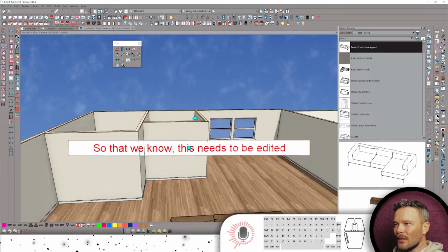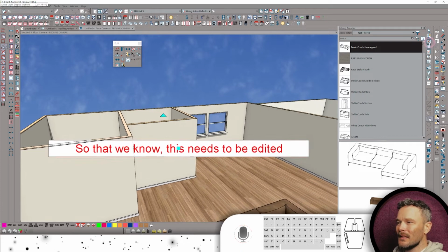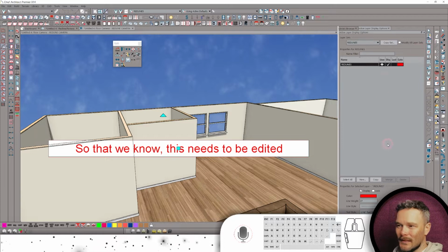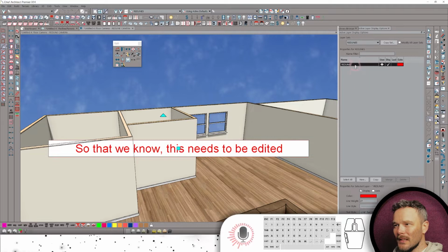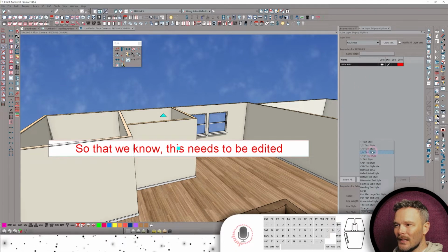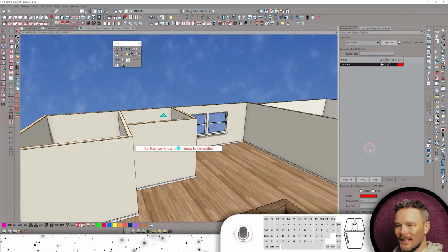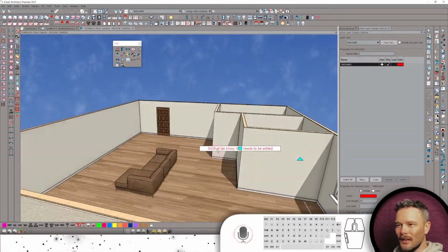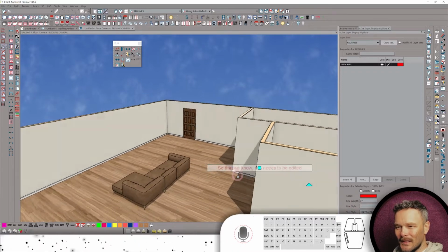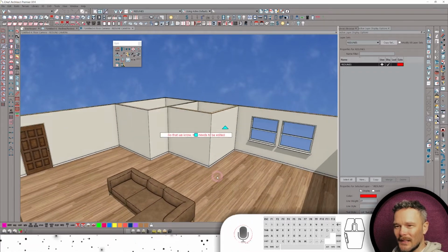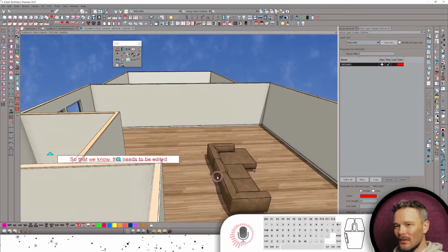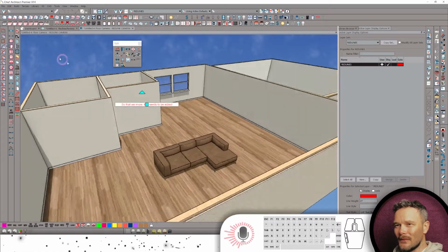Now, if you need to, on the fly, everything in my templates is built using normal text. I do not use rich text. So a big part of this is if we don't want to see such bold typing here, it's really easy to get into this red lines and just change it to a different text size. There we go. Very, very quick and easy to edit all text within my plan. All you need to do is change the text style. I don't use any rich text. This makes it easy to do print sets at any number of different print sizes, you name it. So this is what the red line is for, the red line review.